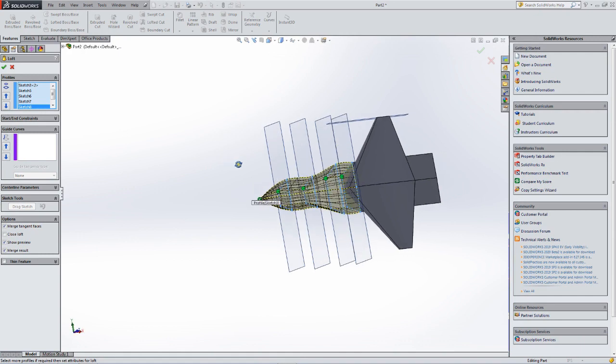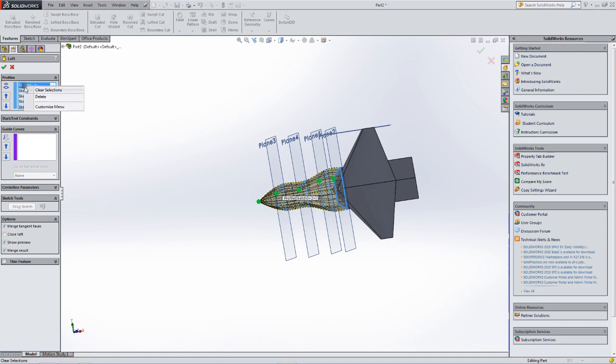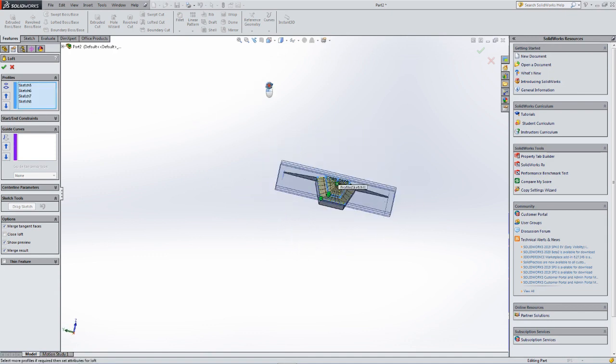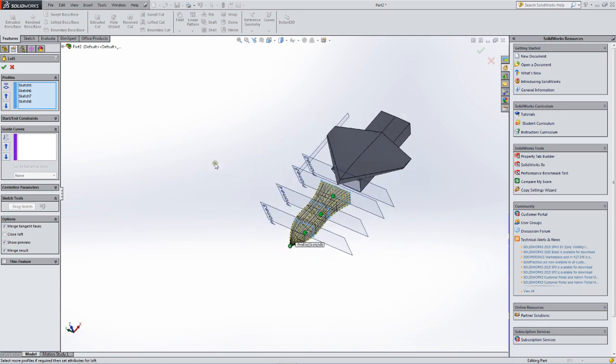What I'm going to do here is take out sketch 3, and we're going to make that a straight loft so that we keep our fuselage slab-sided behind the inlets. We imagine the inlets being here somewhere, and so I'm just going to right-click and delete that. And now that's the shape of my nose section, and then I'll put a different loft in there to join the two.